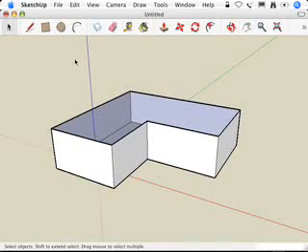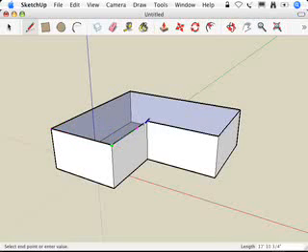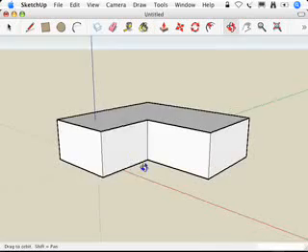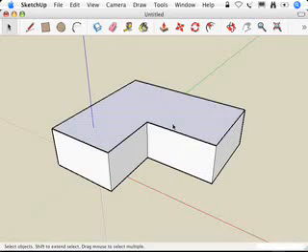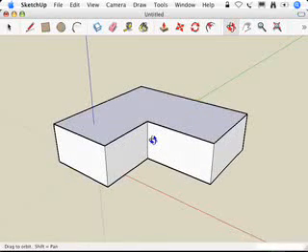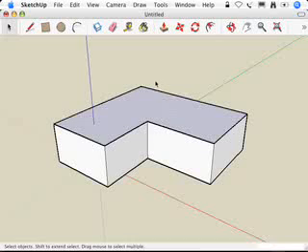Okay, so the way that I describe how to do this in the book is to use the line tool to just go ahead and retrace by snapping to all these little inference points. Retrace the outline of the face that you'd like to appear. So there I have it. Right there I just created a face by creating a whole bunch of coplanar looped edges that I wanted to exist so that I can create this roof.